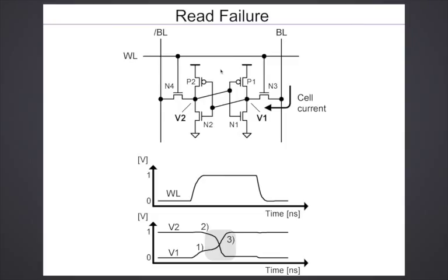So because of the large number of cells involved in a memory and the small size of the cells, you have to really look at the behavior of the memory cells in the tails of the distributions, five sigma. You look at the mean plus five sigma behavior, mean minus five sigma behavior, and ensure that things are working properly across that larger range of deviations. So that is where the difficulty comes, because of these small cells and the large variation, they don't scale down properly. So how do you fix this particular problem?